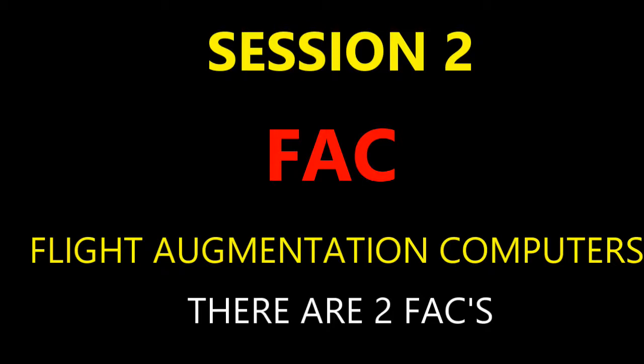So with here, remember I mentioned the SFCCs, your slat flap control computers. You have your control computer 1 and the other one computer 2. So with the combination, if you have a failure of both the SFCC1 and FAC2, okay, so 1 and 2, but one's the SFCC, that would be the 1, and then the FAC2, if those both are failed, then you're not going to have that alpha floor protection. If you have the flip-flops, you have SFCC2 and FAC1 failure, that's also another cause of that loss of protection. The other part would be a dual ADIRS failure, or you have the dual FMGC failure that would also just not have that protection anymore. So just giving you a heightened awareness of some possibilities here when you have that loss of protection.